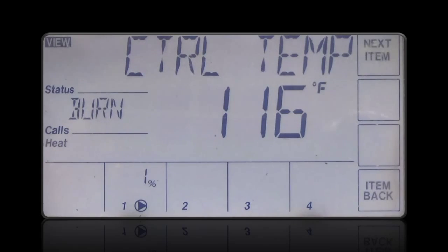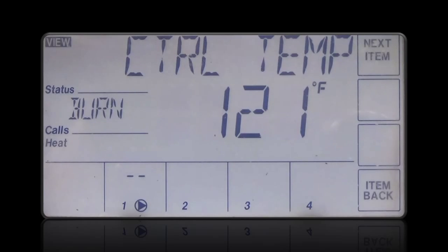When the control temperature reaches the set point temperature, the call for heat ends. The burner shuts off and the ignition post-purge sequence initiates. The sequence field now shows purge and the blower countdown message is displayed. Following the 15-second post-purge, the unit returns to an idle status until the next call for heat period. See the Conquest Installation and Maintenance Manual for additional information on the BTC2 parameters and adjustments.